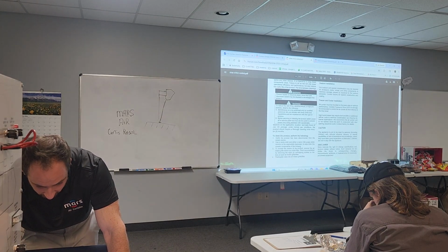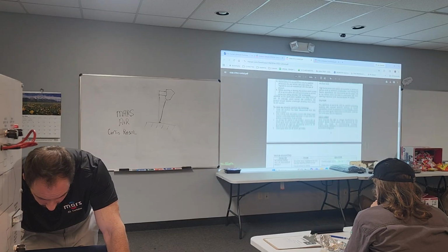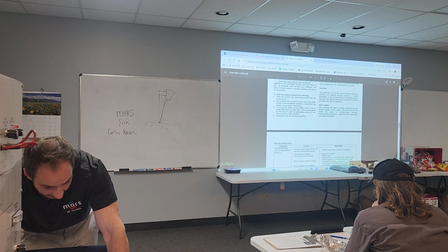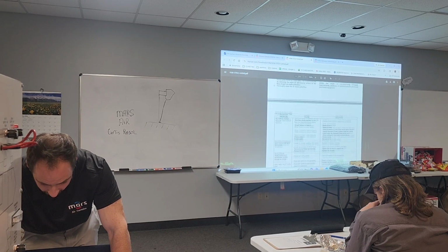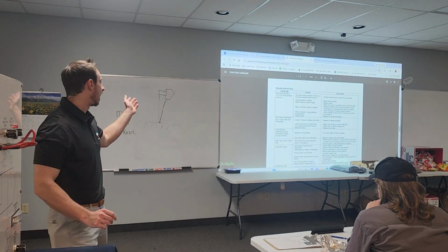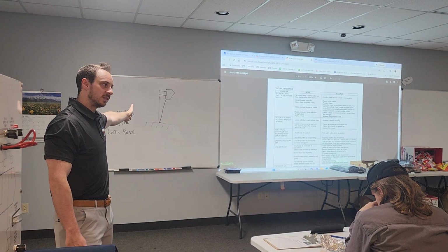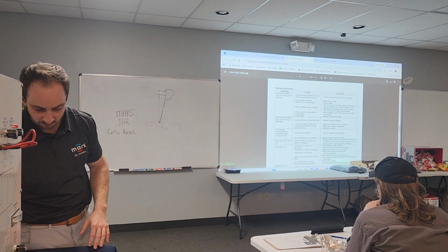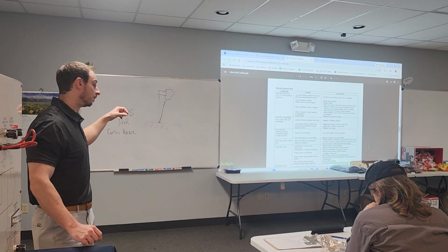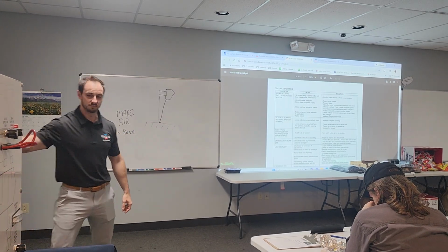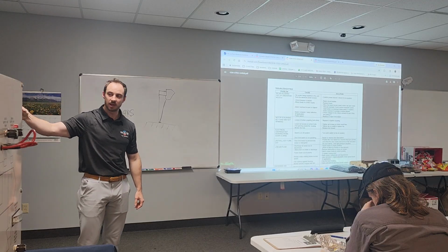There's a startup guide in here. I kind of skipped over that, but it helps you. Again, I already talked about a lot of this, making sure the discharge is pointing at the opening and things like that. You're getting correct airflow, no negative pressure. You can even check that with a piece of tissue paper.